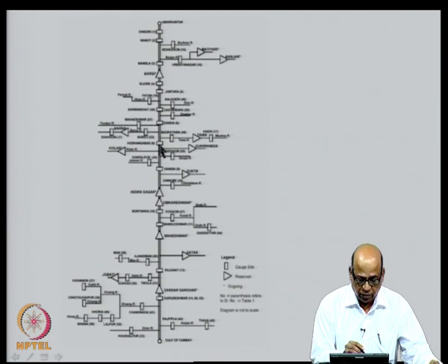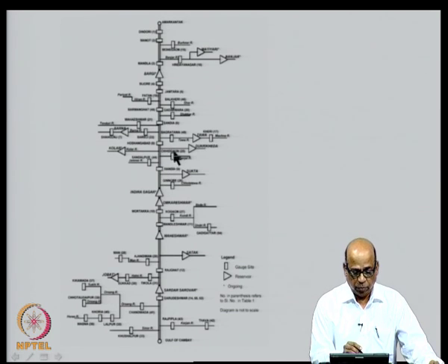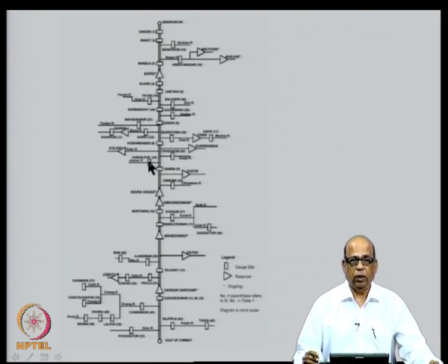So, the flow at Hoshangabad plus the flow at, let us say this is Chitgaon and then this is Sandalpur. These flows will get added to come to Handia. In addition, there is also an intermediate catchment that also contributes to the flow at Handia. Therefore, when you plot the double mass curve at Handia, the Handia flows must be greater than the accumulated flows at all these 3 stations together. That is what we examine in the double mass curve.